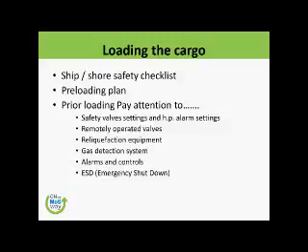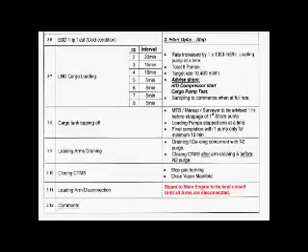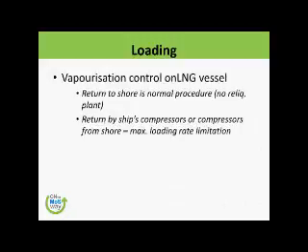So this is just the sequence of operation which we are going to do, because we are going to take the liquid from the shore and give the vapor to the shore for our cooling down process or gassing up process. So we'll anyway have to do this, and we'll do it prior to the loading. I will stop here, folks, and from now on we will do two different exercises for gassing up the tanks and cooling down the tanks.